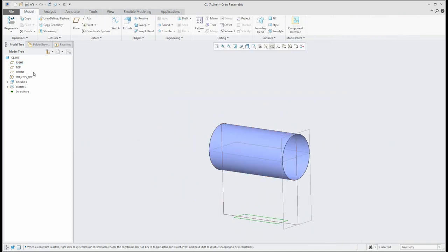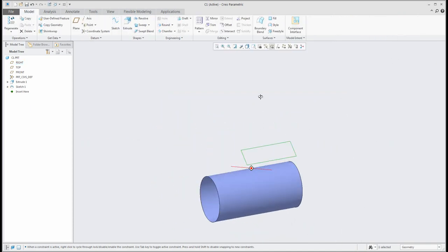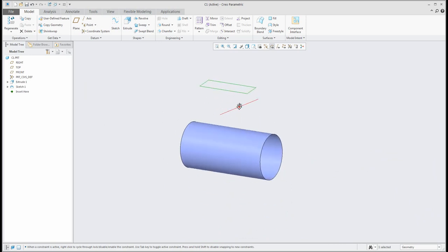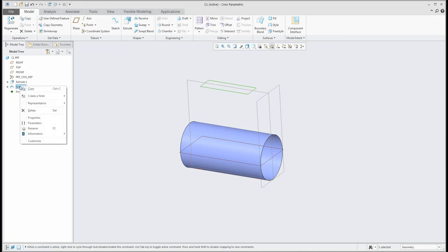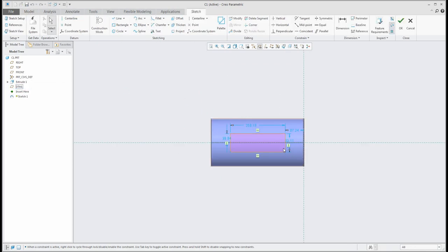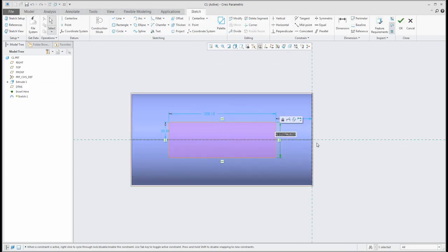I'd like to explain what it means: if you create right now the projection of that sketch, the system will automatically project it, but the length of the line will not be the same as in the sketch. But I'd like to show here, if I select the definition in my sketch, that the length of the line is 100 millimeters, for example.